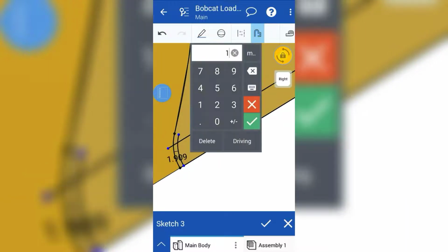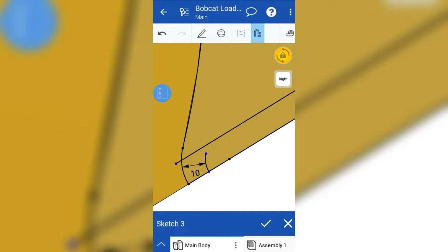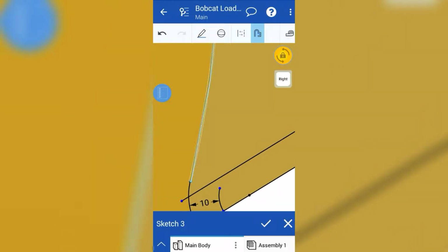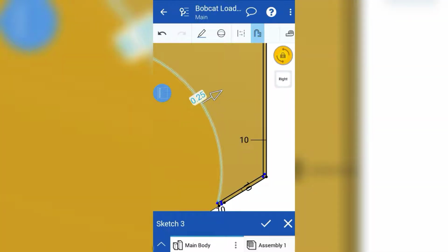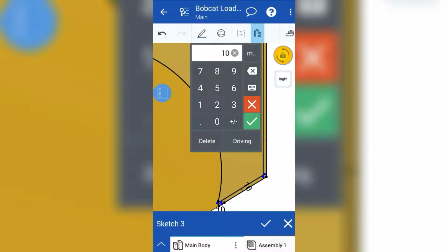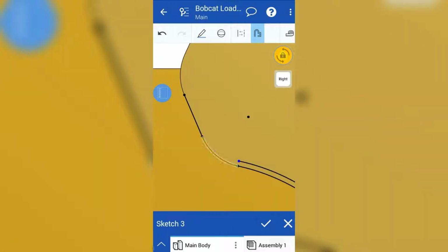Inside it is 10 millimeter. Select the tangent arc. Selected the tangent arc. After that we are going to select the center point arc, and also the offset distance is 10 millimeters. Again, choose the region of fillet in opposite direction, make it 10 millimeters. Select the remaining part, that is last part, which is a line, and give it offset up to 10 millimeter.